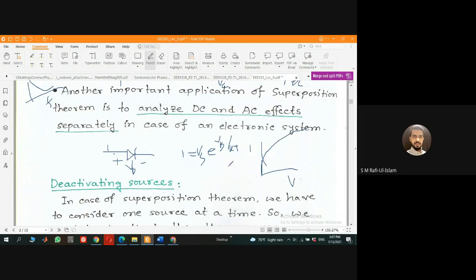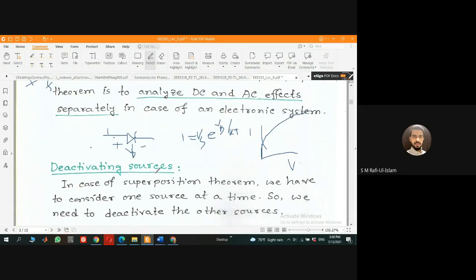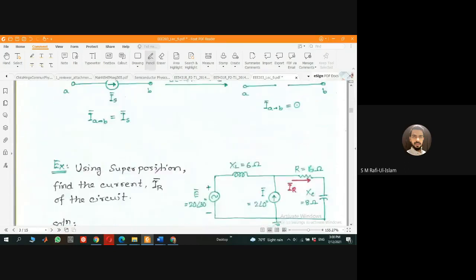So that's why we are saying this is a nonlinear device, or any device containing actually the diode would be called a nonlinear device. And for that actually circuit containing diodes or any sort of actually nonlinear device, we can never apply the superposition theorem. Okay, even if I had actually enough time, I could actually explain why the superposition theorem cannot be actually applicable in nonlinear devices, but probably it will take much time, and that should be enough whatever we have learned here.